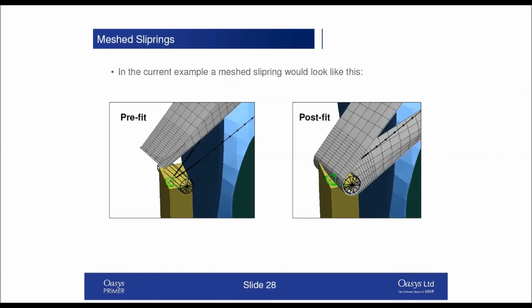And what they look like is Primer uses an imaginary cylinder of a given radius that we specify, and it pulls the belt around that radius. We have to give it a transition distance of the coarse to fine mesh, and an angle which controls the fine element size. The idea is that Primer would create this belt form, and then you would have your own buckle mesh in there. So Primer doesn't use a mesh or anything; it just uses this imaginary cylinder. And that was added from version 13, and it's in there in 14 as well.